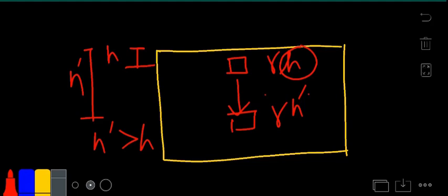As we go further to the deepest parts of the ocean, the pressure ranges become so high that a rigid body analysis cannot be done on that body, though it is a rigid body. Suppose it is made of a very rigid substance like carbon steel. When we put it in the surface region of the water, the analysis can be done through a rigid body analysis. But when we take this body to the deepest parts of the ocean, the pressure ranges change substantially, such that it is subjected to very, very high pressures. In those conditions we cannot do the rigid body analysis anymore. We have to go for the deformable body analysis.